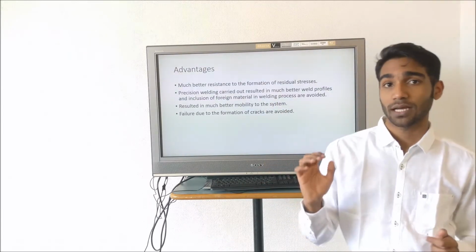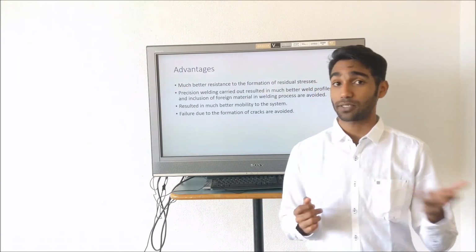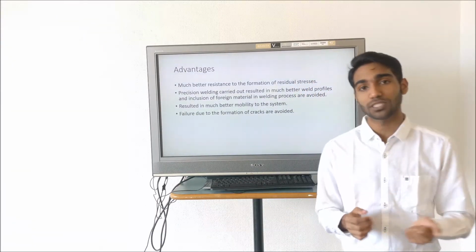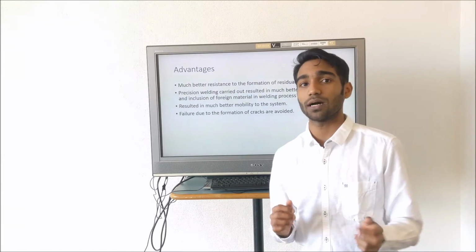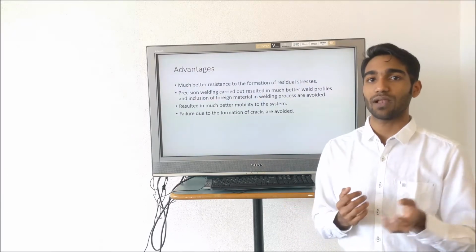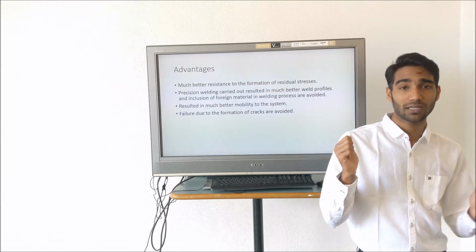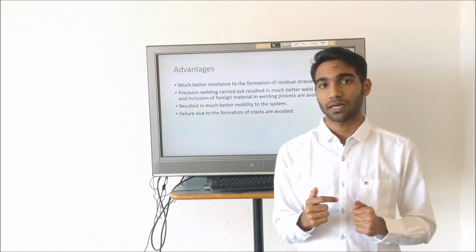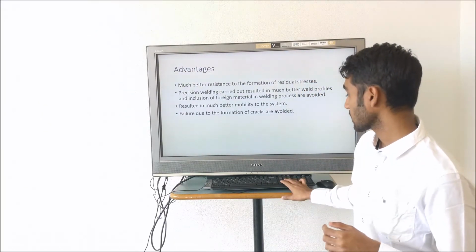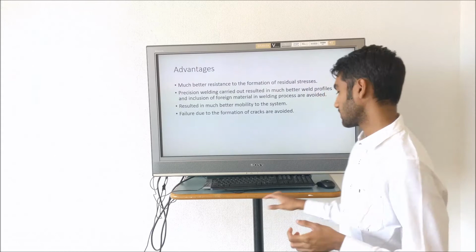Now the advantages that the new design poses. Because of the elimination of residual stresses, the premature failure of the structure can be avoided. As we make use of precision welding, the weld profiles are more even, and there are no foreign materials included in the weld materials to weaken the structure. Also, the introduction of the sleeve imparted the much required mobility to the system, which is a major factor in reducing the formation of residual stresses. A combination of all this resulted in the elimination of crack formations.